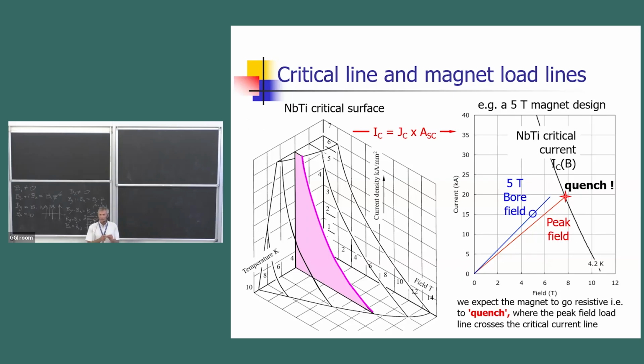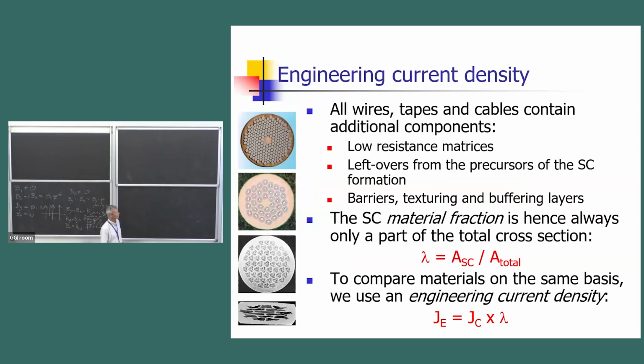Now imagine that I ramp the current. What happens? I'll be moving up on this line until I reach the critical conditions. And then, as they said, above the critical conditions, you're no longer superconducting. So you start Joule heating. So there's a resistive heat. And this phenomenon is what we call a quench, exceeding the critical properties of the superconductor. That's when the magnet quenches. All right, so